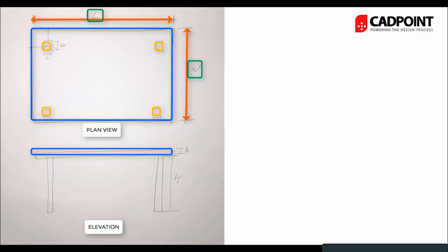always be at a fixed distance for this particular family. And the table leg thickness will always be the same as well, but they'll always move as the table moves. So that's the key thing when you're sketching it out. And then we'll be able to control the actual height of the tabletop as well, and we'll make sure that all of the legs move. As the table height moves, we want the legs to move up with it as well. So we want those particular pieces of geometry to be attached to that piece of geometry.